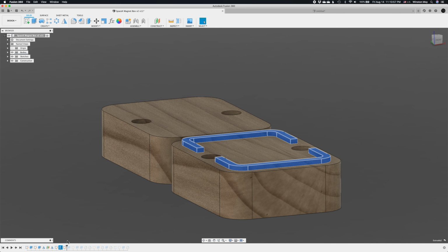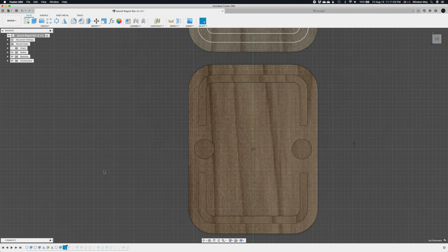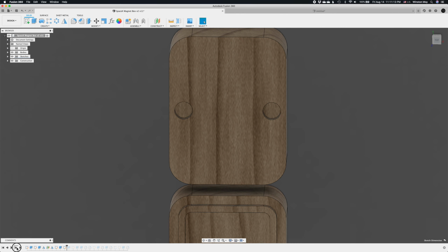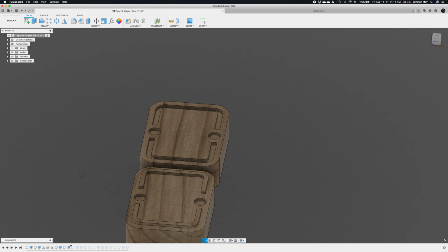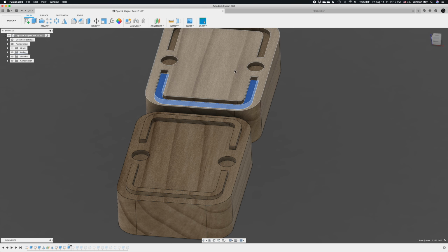So I extruded this out. This is, again, another parameter, the lip height. Next sketch is just for the inset feature here. That basically matches this, and then I will remove a little extra material on top of that.